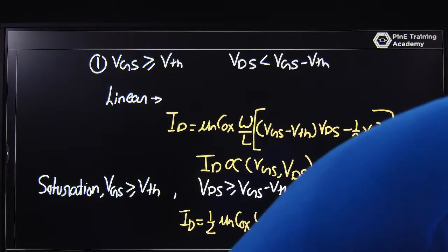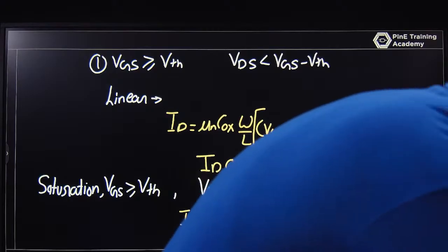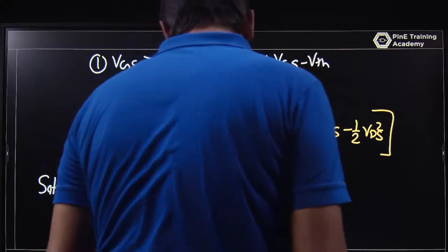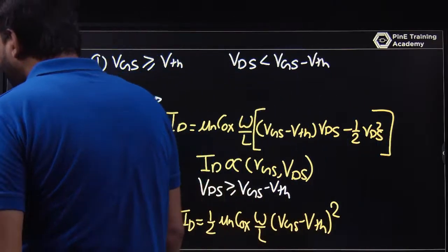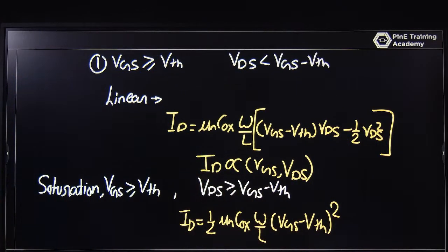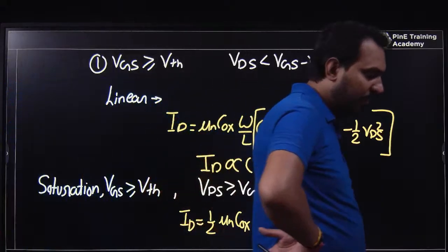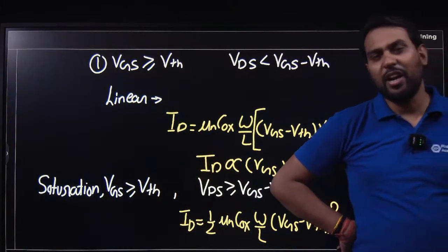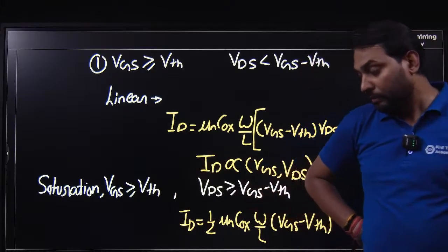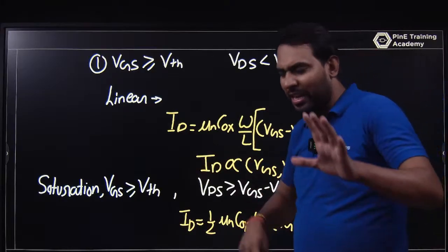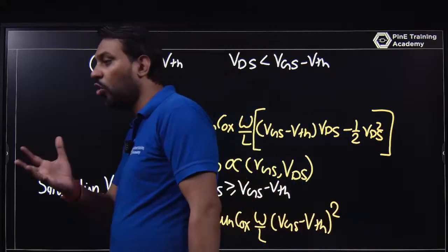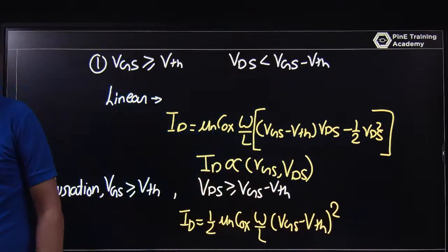Why is FinFET ideally not used for analog circuits? FinFET is not ideally used for analog. Of course FinFET is used, but it requires a lower technology node, where you find less second order effects, such as sub-threshold conduction. I have an example of this. Do you know what sub-threshold conduction is?